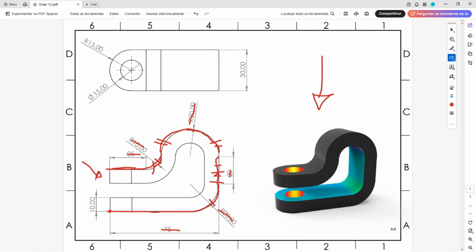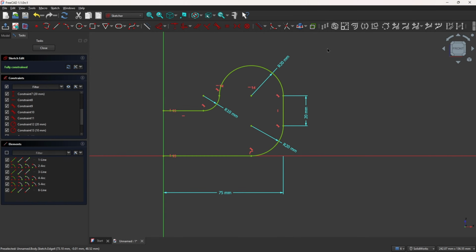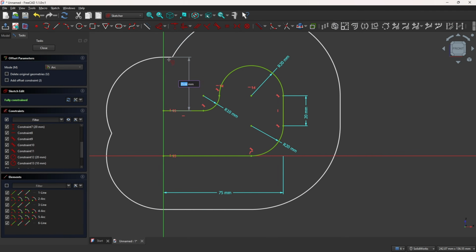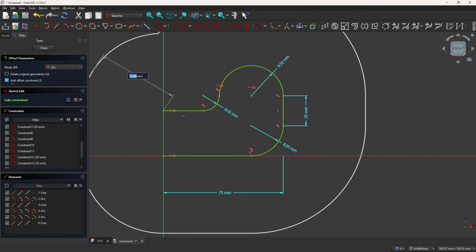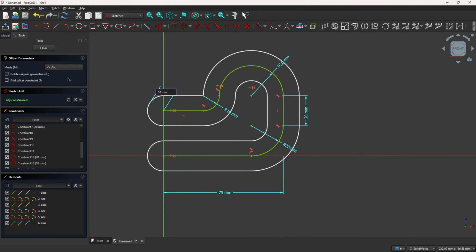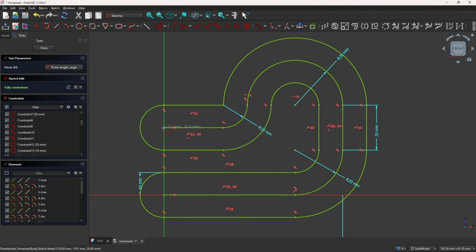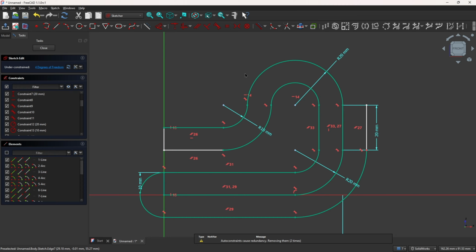And now to create the outside here, the inside lines here, we will use the offset, and the offset is 10 millimeters of distance. So select all these lines and go to offset, and in the mode, select here add offset constraints, and the distance here is 10 millimeters and press OK. And now select line, make a line from this point to this point, from the midpoint to this point, and select trim, cut the outside lines and arcs,